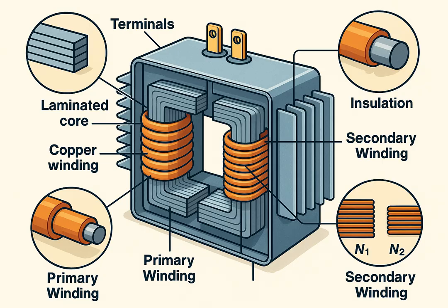Additionally, laminated cores help reduce hysteresis losses, another type of energy loss that occurs as the magnetic domains in the core material realign back and forth with every AC cycle. So, in summary, although the core looks like a solid structure from the outside, it's actually made of carefully engineered layers to maximize magnetic performance while minimizing heat and energy loss.